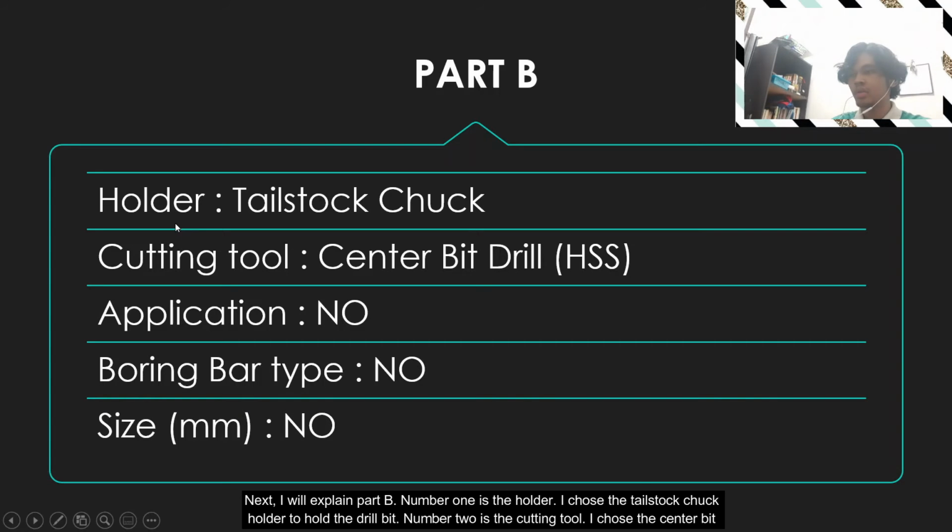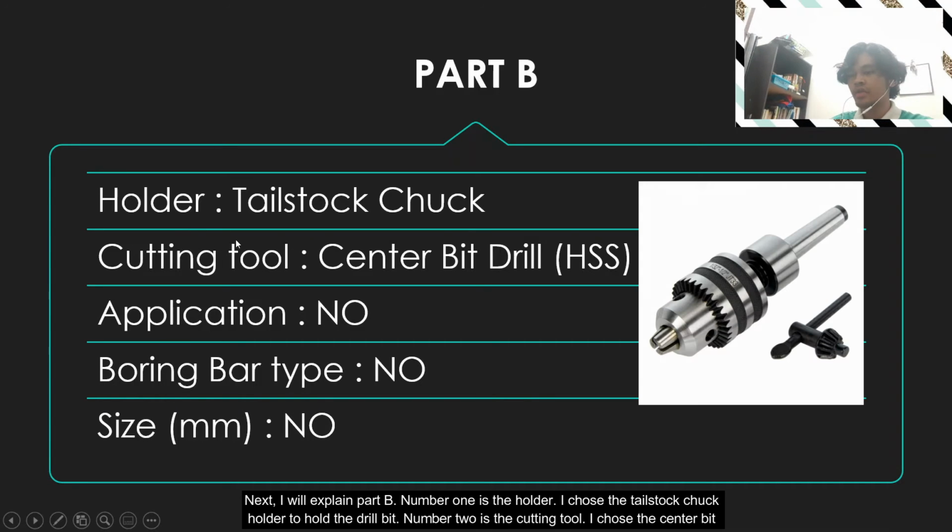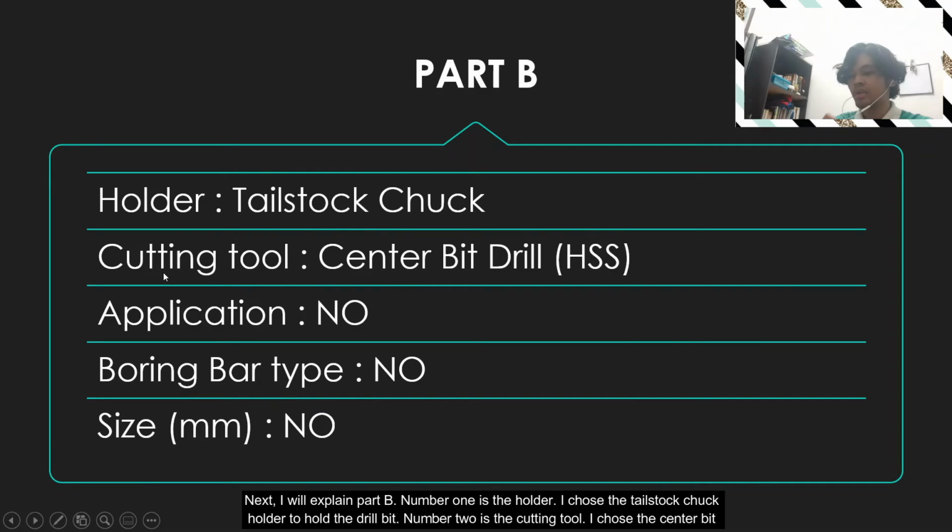Number 1 is the holder. I choose the tailstock chuck holder to hold the drill bit. Number 2 is the cutting tool. I choose the center bit drill HSS cutting tool. This is because this bit drill is designed for center drilling.